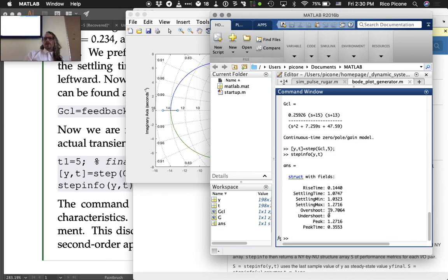And we got down to a percent overshoot of like 19.7%. So we're pretty much right on the money. You could probably iterate a little bit more and get closer to 20%. Oftentimes, you want it to be below something or above something. So probably we want to be less than 20% overshoot. But we're pretty right on the money for overshoot now. So now we've got the overshoot that we want using this gain of 0.35. And our settling time is 1.07.